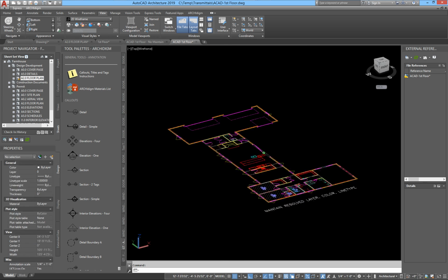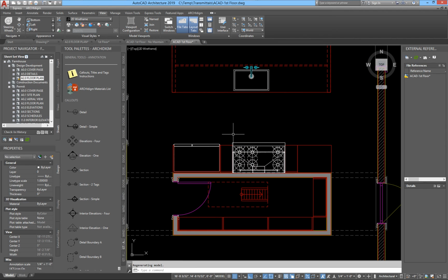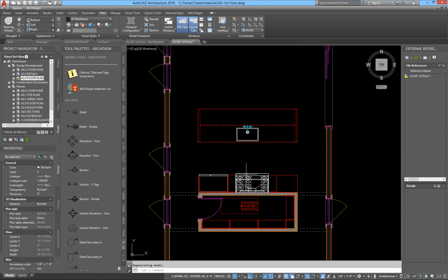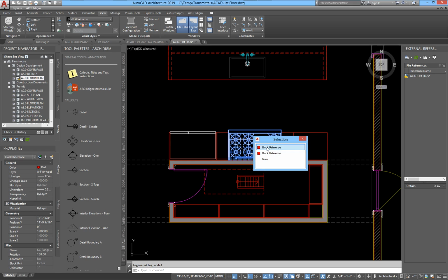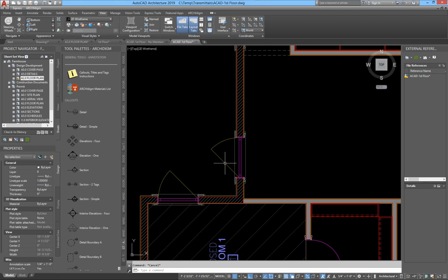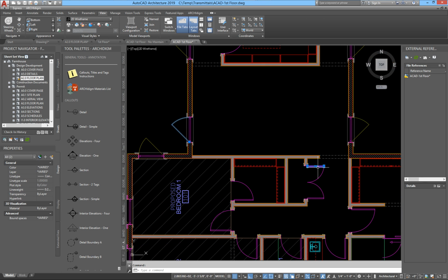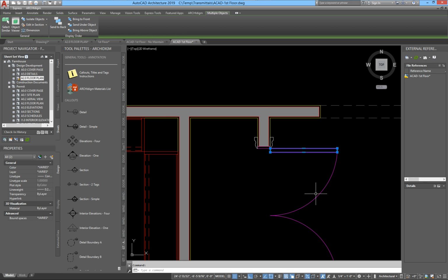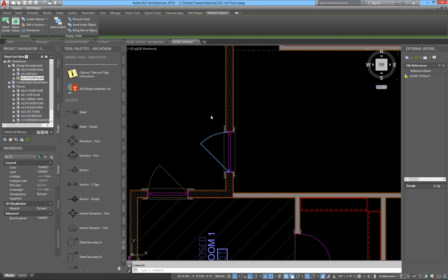We look at it in 3D. We see it's pretty much a flat line work drawing. You'll notice some of the objects, these are the multi-view blocks. Some of them had some issue in terms of layer color line type stuff. When you select it, of course, these are blocks. Some of these you're going to see 2 blocks because there's a masking block underneath it. And when we select a window, for example, or even a door, notice how it behaves in terms of the selecting process.